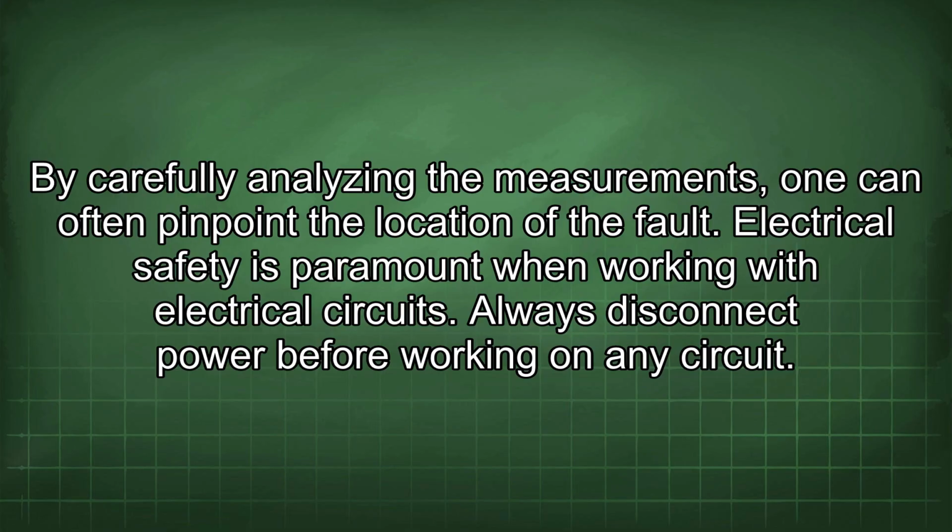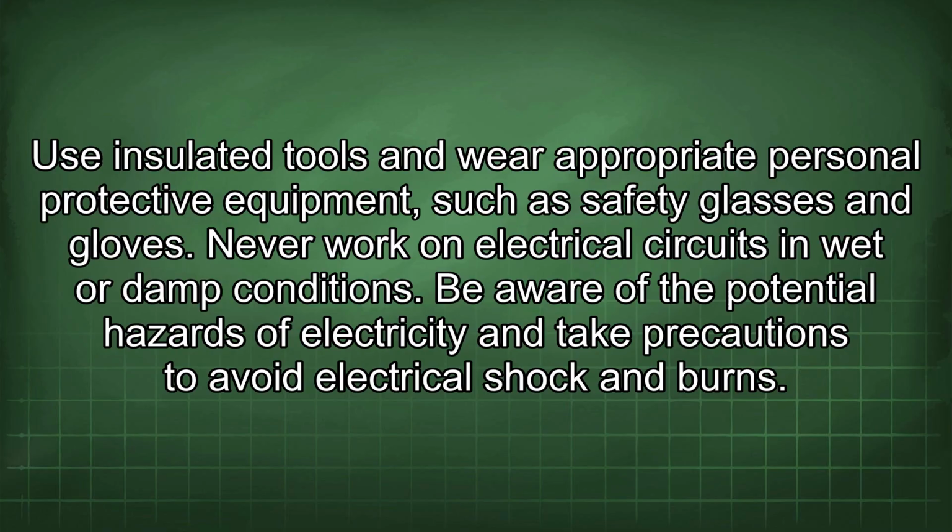Electrical safety is paramount when working with electrical circuits. Always disconnect power before working on any circuit. Use insulated tools and wear appropriate personal protective equipment such as safety glasses and gloves. Never work on electrical circuits in wet or damp conditions. Be aware of the potential hazards of electricity and take precautions to avoid electrical shock and burns.